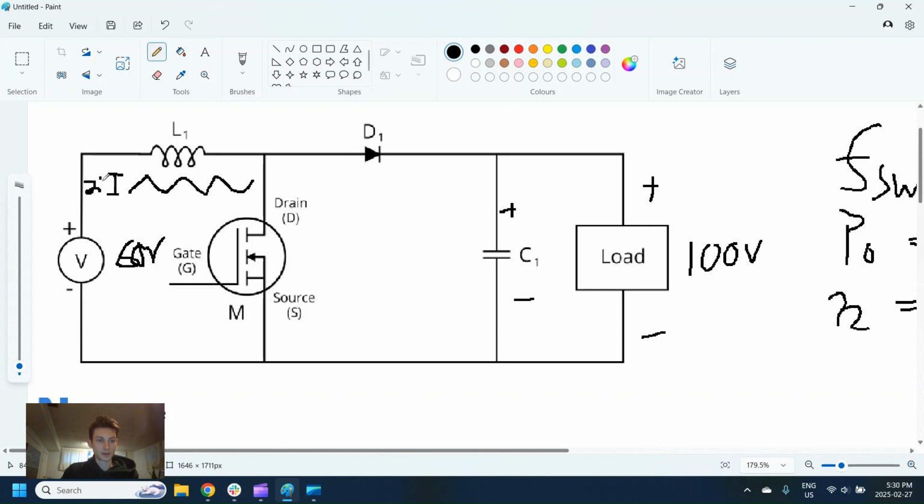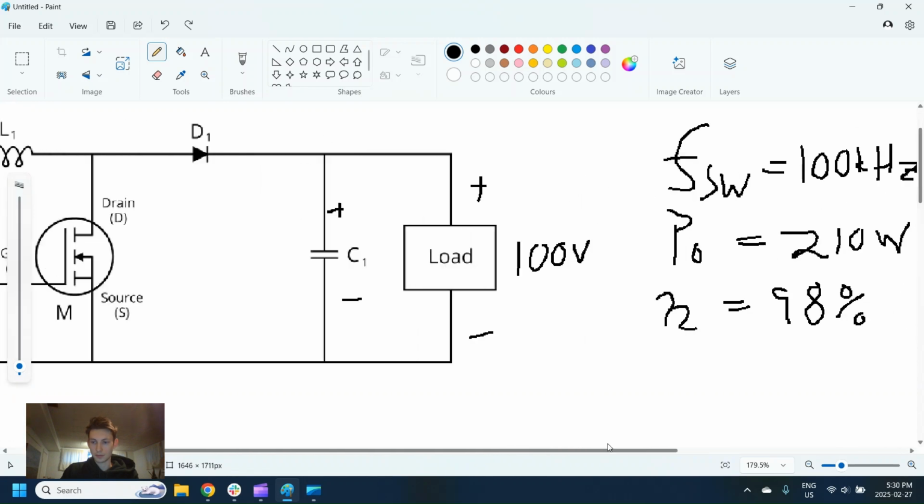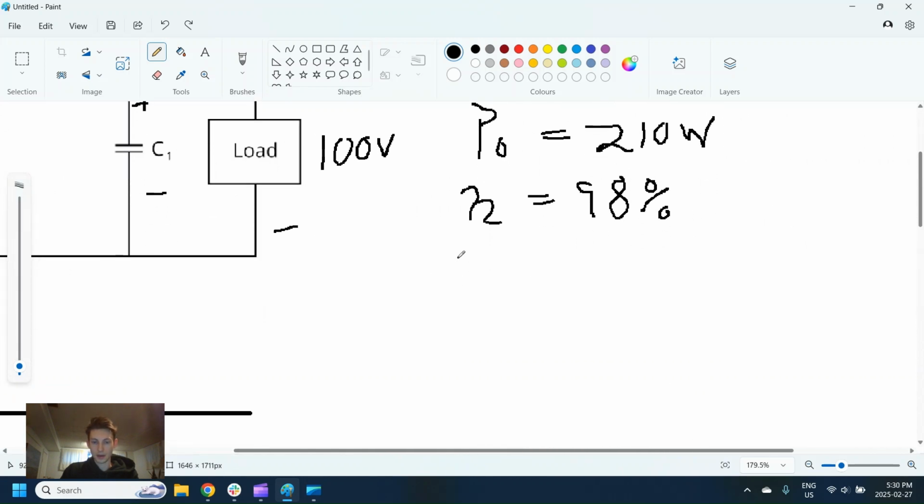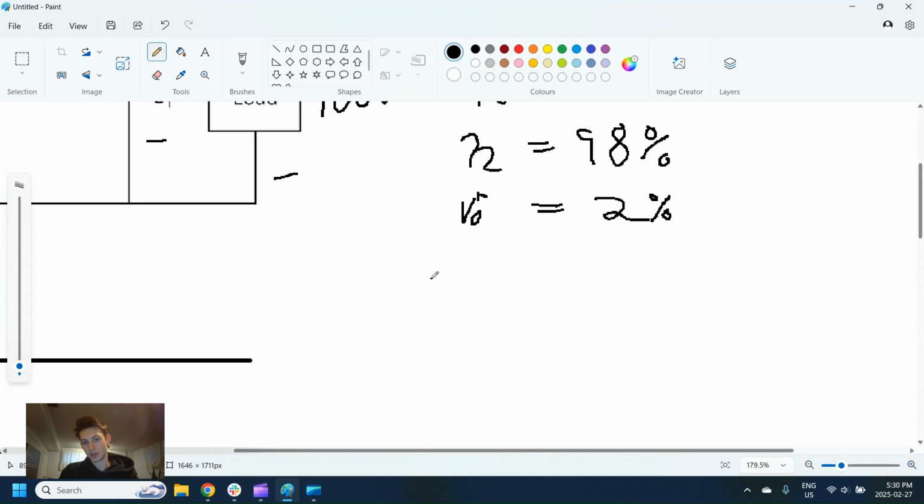So if it was, for example, 20%, which is what we're going to use for the inductor, that means 20% from the top to the bottom. This is as opposed to 20% above the average, which would be that value there. So let's write that down here. A voltage out ripple of, let's say, 2%. This is just arbitrary. For this project, 2% is high, but not insanely high, so we'll stick with that. And the current through the inductor ripple is going to be 20%.